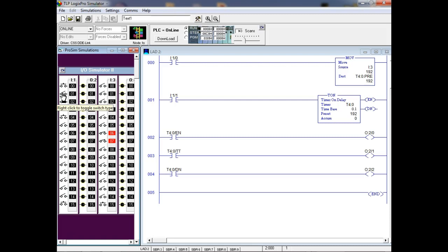So if I'm inputting from BCD switches, your PLC doesn't know that. It looks at it as binary, unless you have an instruction that converts over to BCD. And we can do that, we just haven't got there yet. If you look forward in your book, you would see there's a data instruction where we can convert between binary and BCD. We just haven't got that instruction yet.